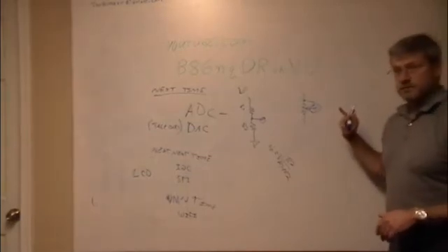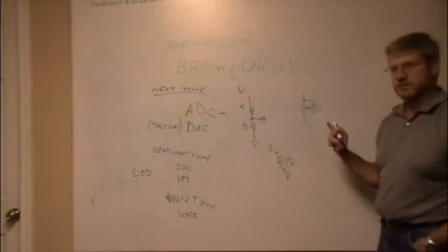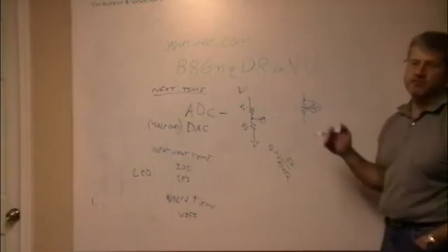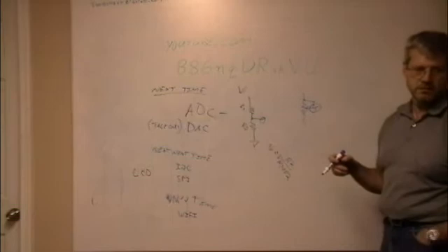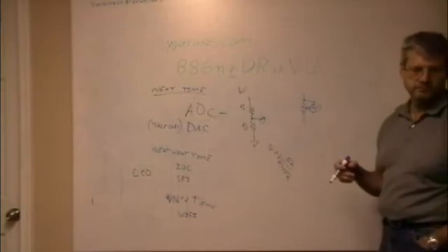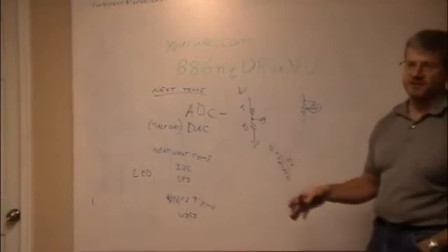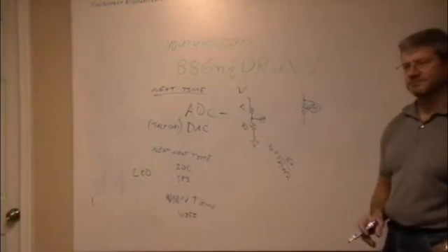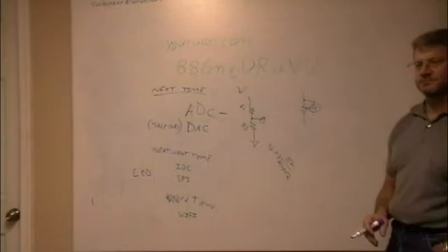So this is a thermistor, and the hottest thermistor I've ever seen is maybe, they can go up to boiling, 200 or 300 degrees Fahrenheit. That was my rudimentary understanding, that your thermistor is good up to a relatively low temperature. Yeah. If you're curing epoxy, a thermistor's fine. If you're going to oven cure, the reason you would set this up is to make an oven to use advanced resin systems like prepregs and stuff like that.